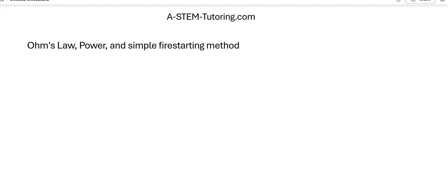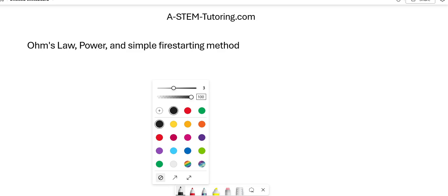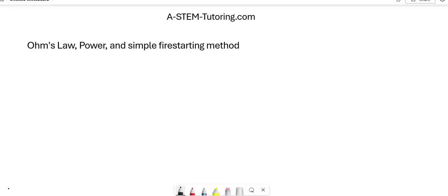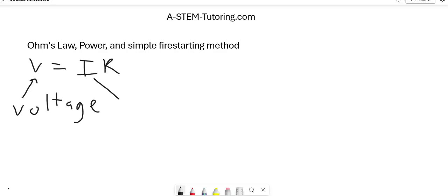All students in basic physics and also in basic electrical engineering courses learn about Ohm's law, that V equals IR, where V is voltage or the electrical pressure, the potential for current to flow. I is the electrical current, how much current actually flows.